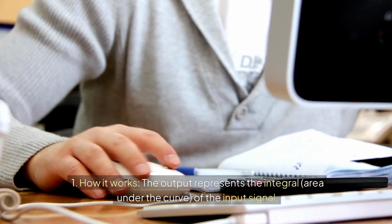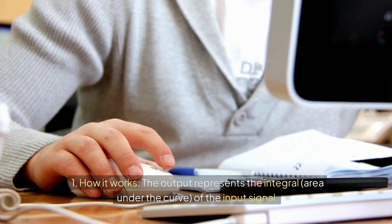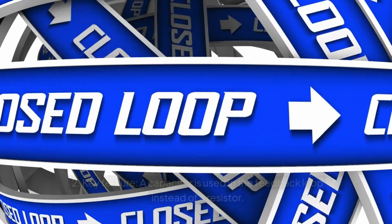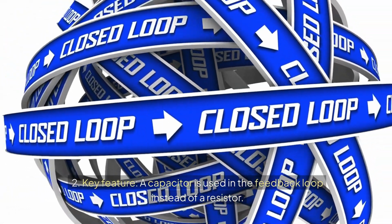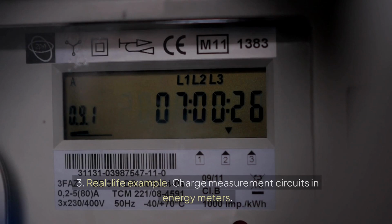1. How it works: the output represents the integral, area under the curve, of the input signal. 2. Key feature: a capacitor is used in the feedback loop instead of a resistor. 3. Real-life example: charge measurement circuits in energy meters.